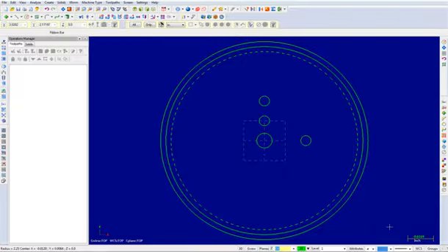Next, we will create tangent lines. In this step, you will learn how to create tangent lines knowing the angle of the lines. Select the Create Line Endpoint command as shown. In the ribbon bar, ensure that the tangent option is enabled and that both vertical and horizontal are disabled. From here, select the Zoom Window button and zoom in on the following area as shown.